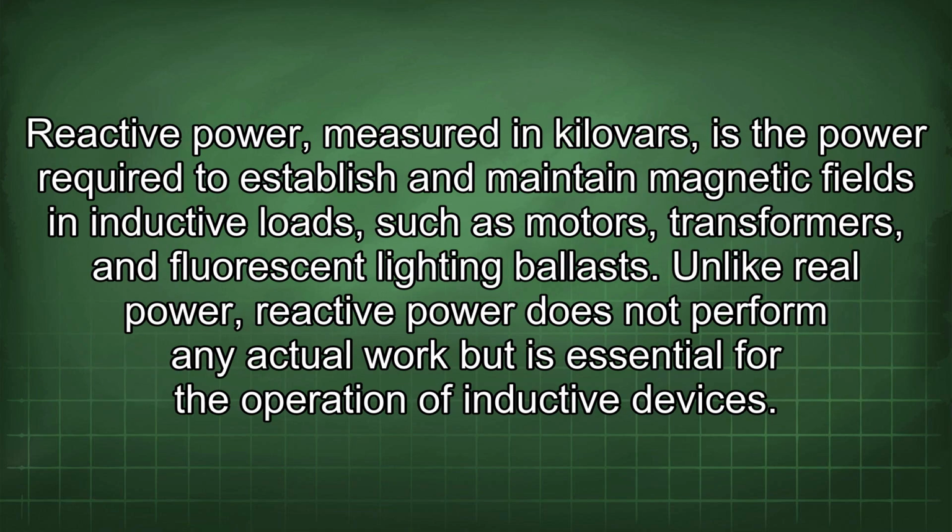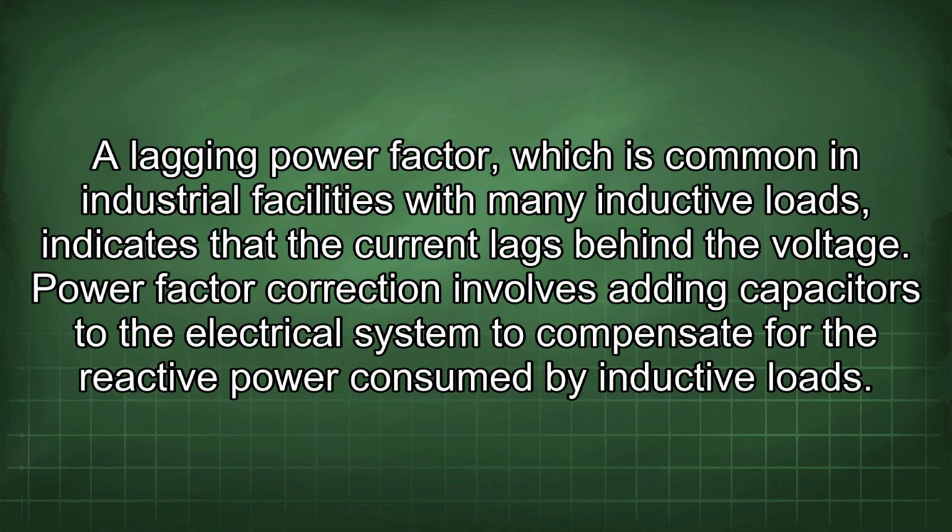Reactive power, measured in kiloVars, is the power required to establish and maintain magnetic fields in inductive loads, such as motors, transformers, and fluorescent lighting ballasts. Unlike real power, reactive power does not perform any actual work but is essential for the operation of inductive devices. A lagging power factor, which is common in industrial facilities with many inductive loads, indicates that the current lags behind the voltage.